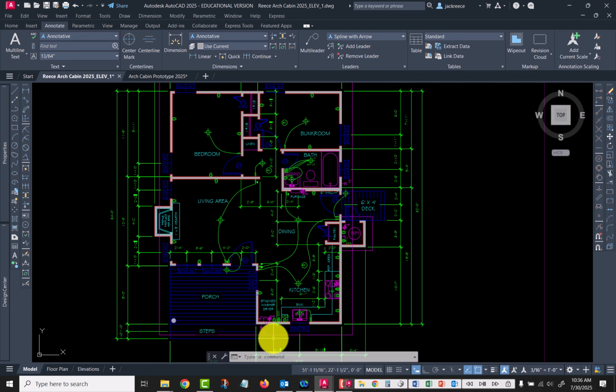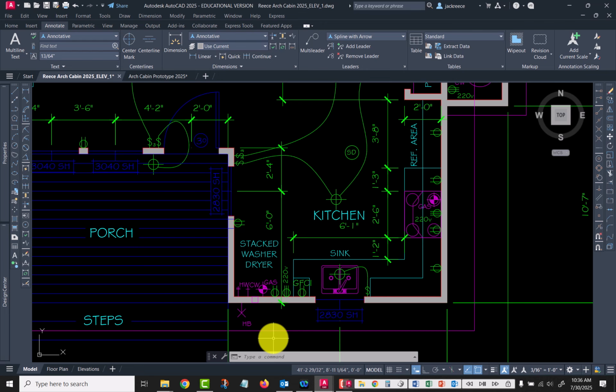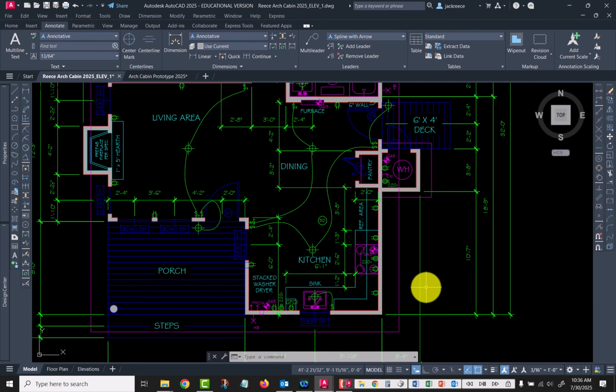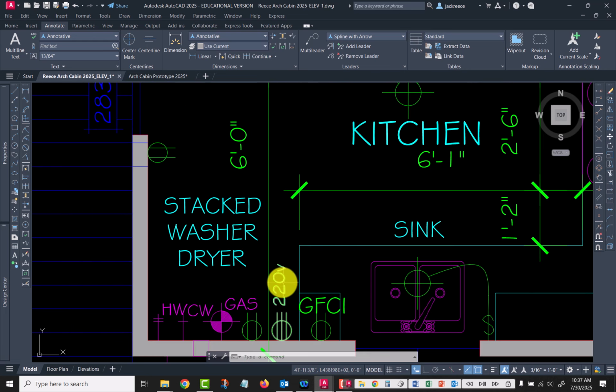So what you'll have to do is explode it. You have to bring one of those blocks in, explode it, and then you can either recreate it back as a block within the drawing with a new name, or you can just group them together and put them on the correct layer. That works too. The 220 volt outlet, same thing down here. The text needs to be relocated.